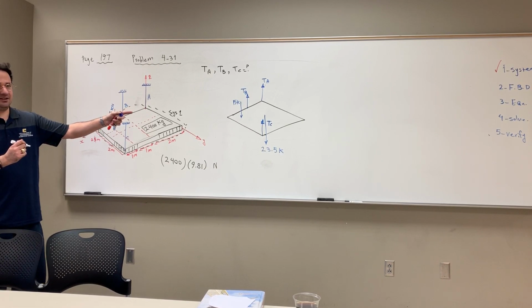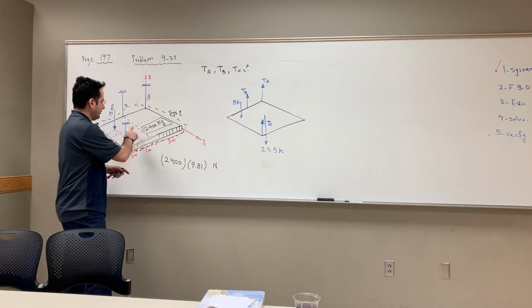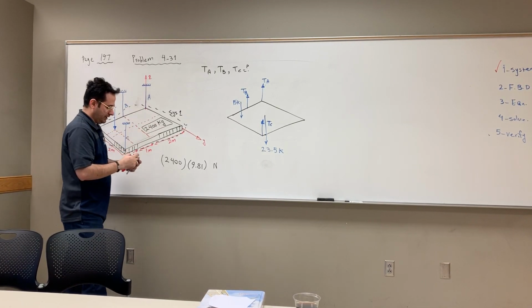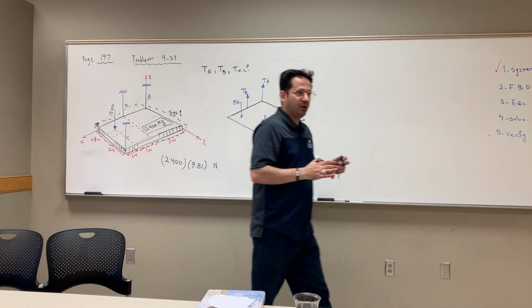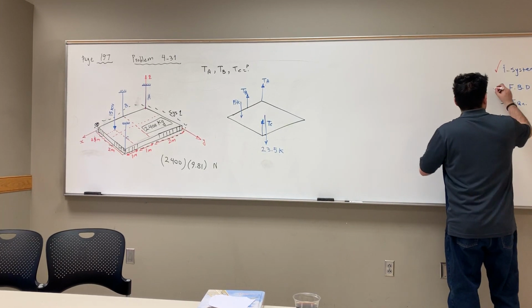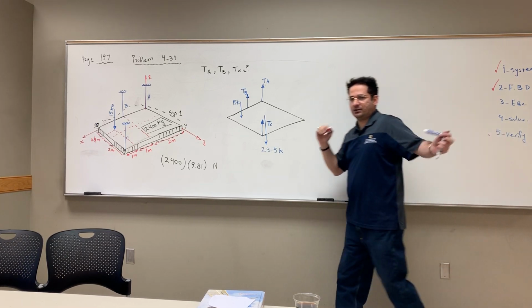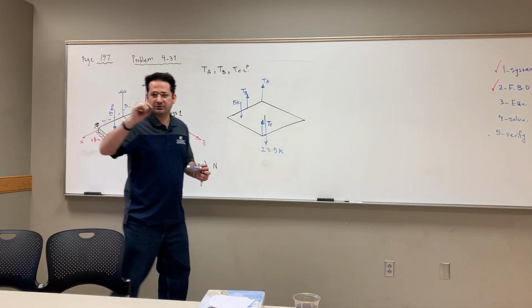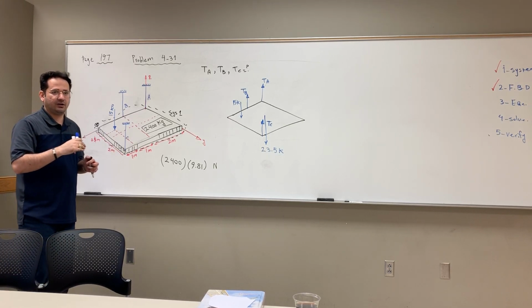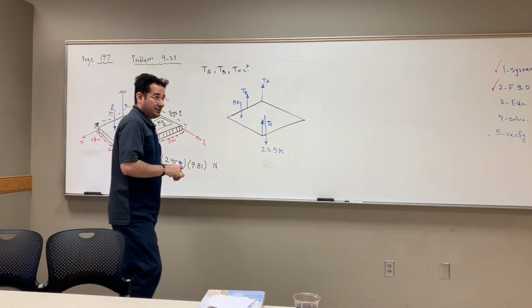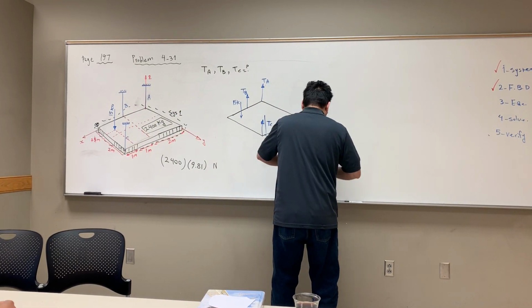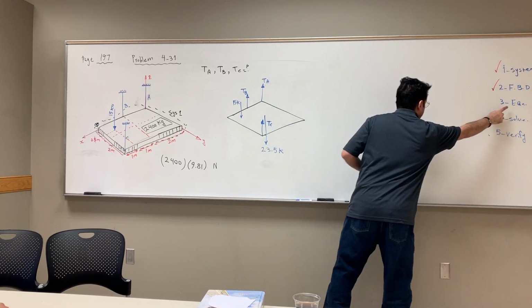So it's actually the value. The point is to come to the geometric center, which is the center of gravity, because it's uniform, right? Now I'm done with the body force, so I'm done with the FBD. Don't forget to put your check mark here. Always try to have a little checklist in your scratch paper to check mark it. Make sure that you know what step you're at, because you can easily get lost during this complicated procedure. Then you go to the next step, which is writing the equations.